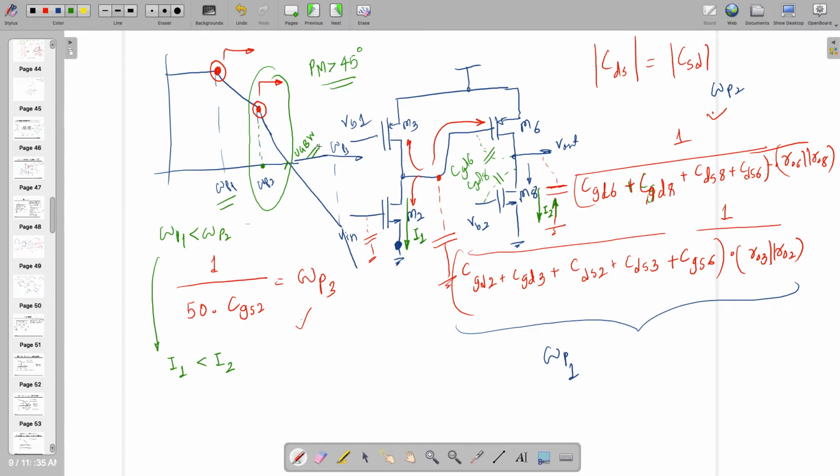So if you are designing a two-stage op-amp, and the first stage has so much current, and it is not working, you have to increase the second stage current by increasing WL. Just touch the multiplier. No need to touch the WL. The unit value of WL has to be the same. Just change the M, right? If it is 1 microampere here, sometimes you realize that you need 10 microamperes to keep the required stability. Sometimes you need even less than that.